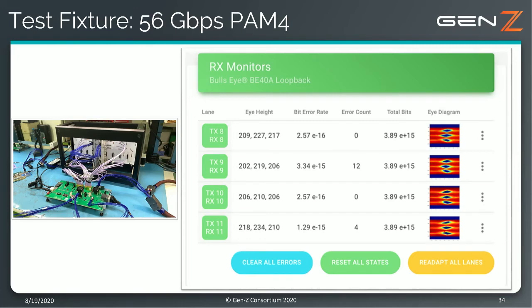And in fact, even the second channel of that has a total bit error count of just 12. So it's managing e to the minus 15 bit error rate. And remember, those bit errors, there's no FEC, no forward error correction in that. The second two rows are, and again, the top one of those has 0 errors.